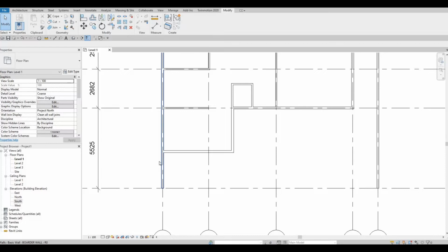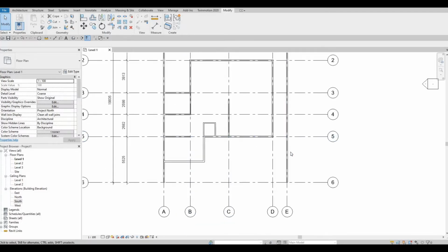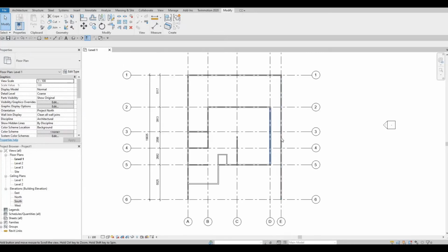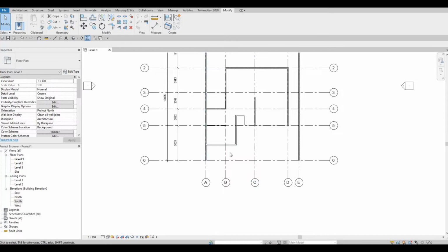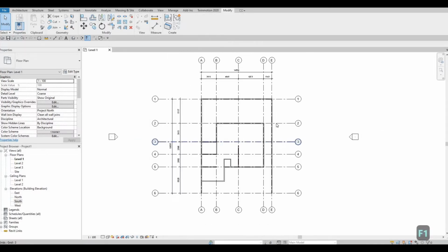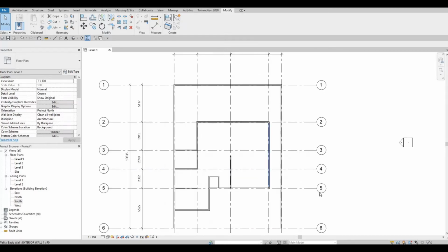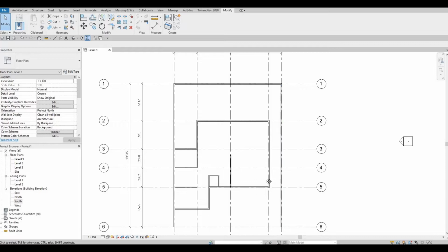And then here as well, because it will be very high for the rendering view. So most of the time I just put it 1000 or 1500, so 1.5 meters high, so that every shot that I have for my view will be proportionally viewed. So that's how I do it. You can definitely do whatever you want, but that's how I do it.